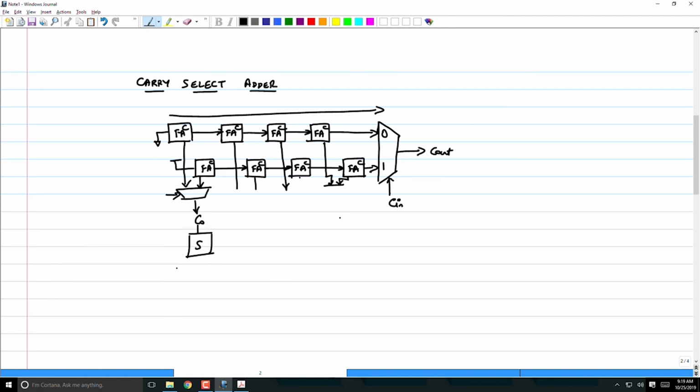Right? You remember when we made the full adder circuit at a transistor level, we used the carry out to create the sum. You can now split that block. You don't have to put that entire thing, because remember now you're doubling hardware. So you double only the necessary hardware. So here this sum block, I am removing and I have only one per full adder set.